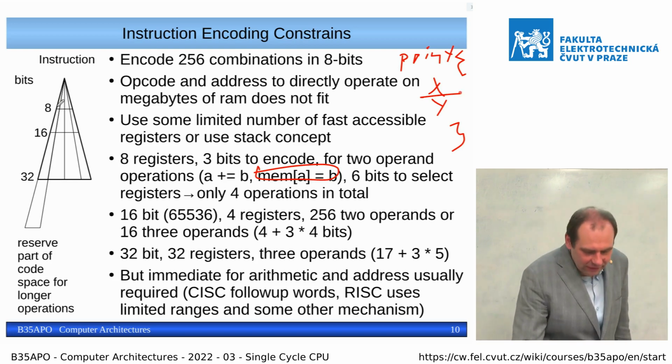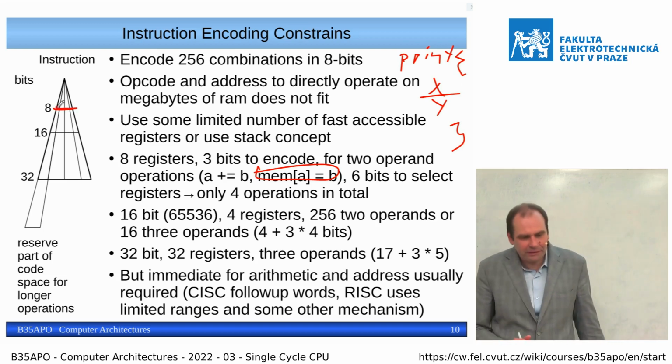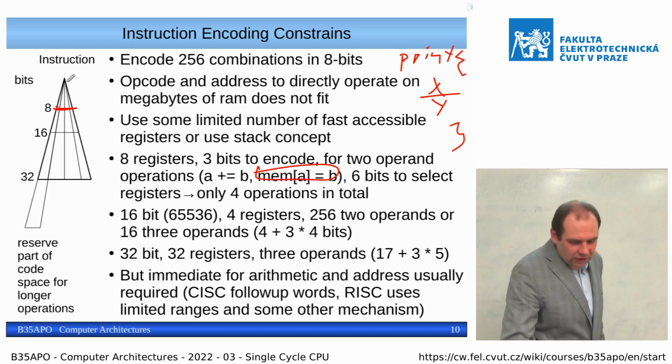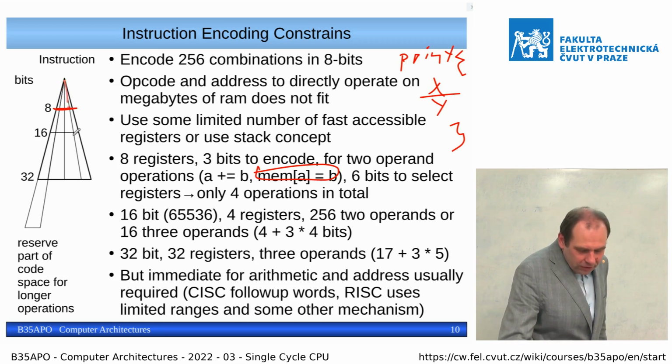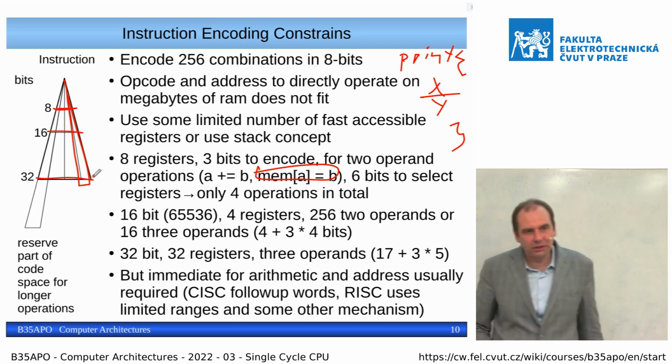Another thing is that, for example, Intel has even on its 64-bit CPU some instructions encoded directly by 8 bits. But such an instruction, which is only 1 byte long, in fact blocks a large area of the 16-bit or 32-bit encoded instructions.